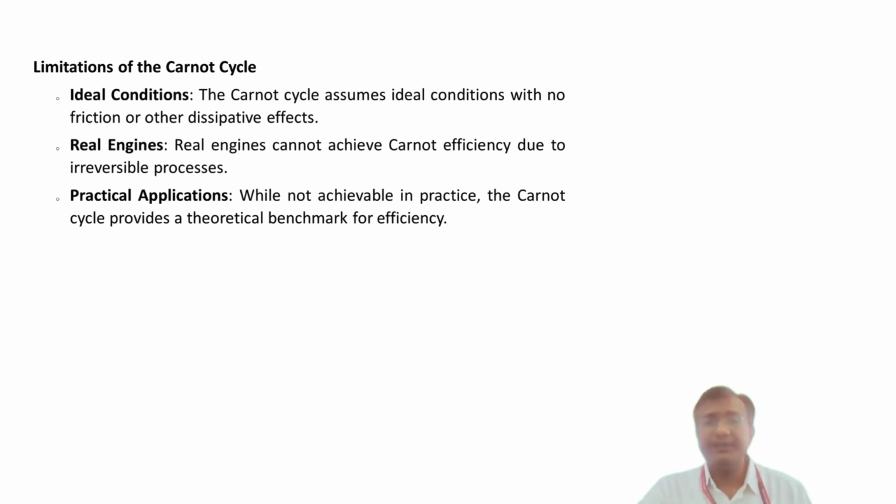Now, we will see certain limitations of the Carnot cycle. The Carnot cycle is an idealized model that provides the maximum possible efficiency for a heat engine operating between two temperatures. However, it's important to understand that this cycle has limitations, and real-world engines cannot achieve this efficiency. Now let's explore what those are. First, the Carnot cycle assumes that all processes are reversible.